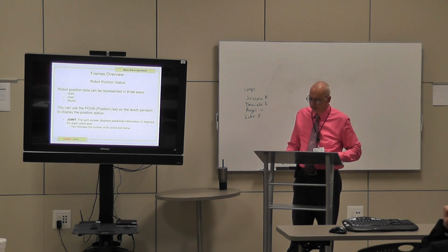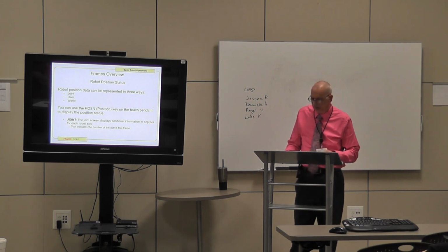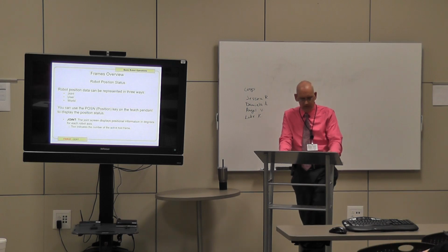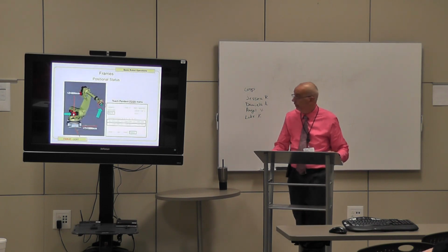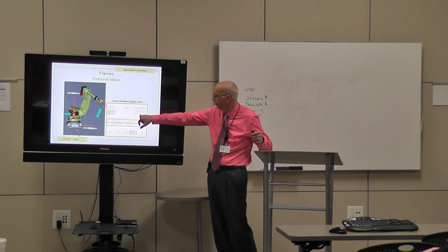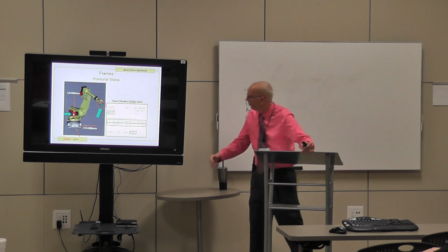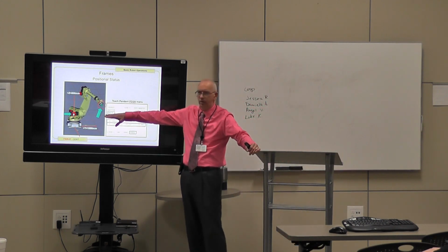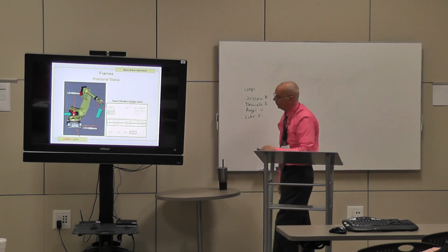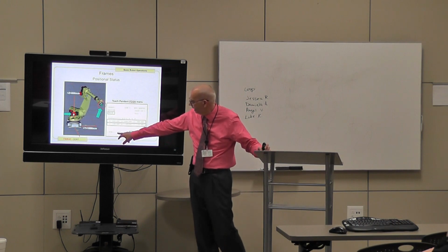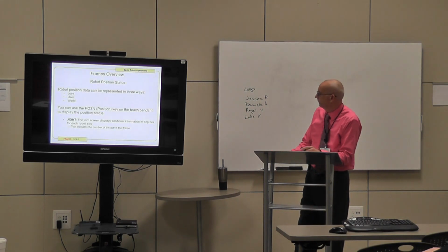The tool indicates the number of the active tool frame. When we look at the screen, if you look right here, see this right here? This tells you that it's tool number 1. That means you're using tool frame number 1, okay? And you are in world, the world position, and so these are going to give you readouts in millimeters, okay? If we were in joint, this would be highlighted, and these would be written in degrees. Make sense? Okay.